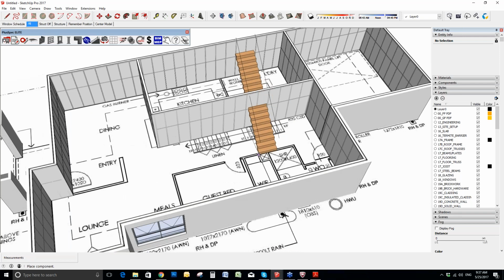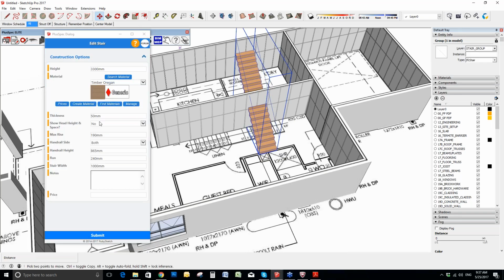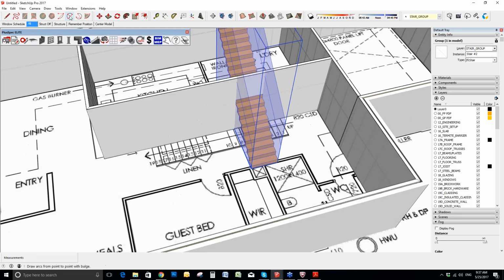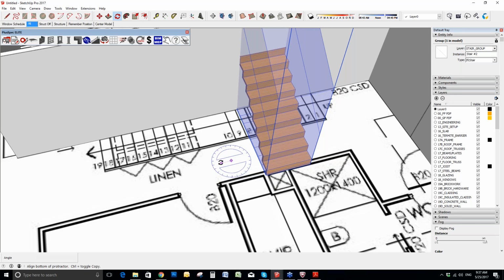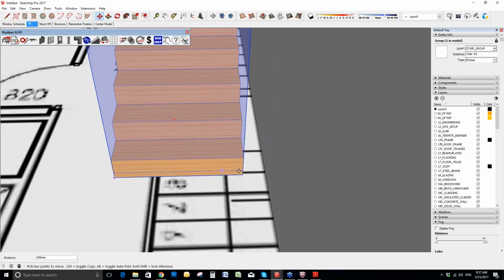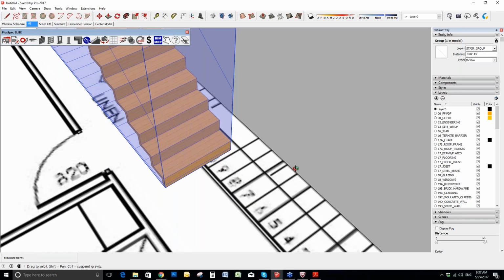And now you can obviously change the height to suit. Maybe you don't know it. I like to put the head height, so show head height, which means you're going to have less error for your first floor. You're then going to use the SketchUp rotate tool, and this gives you the ability to simply rotate it. Using the SketchUp move tool, you can move it in place again like we've done for other things, and you can place it where it needs to be in your project.